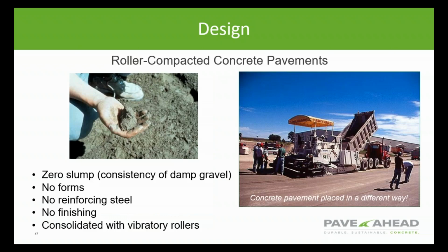So another paving material that may be used in industrial facilities is roller compacted concrete. RCC is an attractive option because it's low cost, it's an easy preparation, high volume production, takes minimal labor, high strength and durability, and its proven performance. Some benefits include economical, high load carrying capacity. It eliminates rutting and spans weak subgrades. It's excellent freeze-thaw durability. It's simple, it's fast to construct. There's no forms or finishing, and the light surface reduces the lighting requirements.